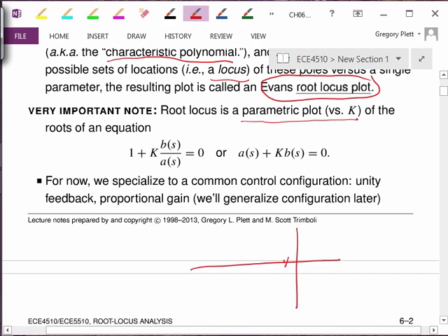And we've seen root locus plots that have poles that start there, and one goes up and one goes down. Something like that. That's an example of a root locus plot. A parametric plot is one where you can see the pathway that the pole will take, but you can't directly from the plot infer the value of k that put them there.